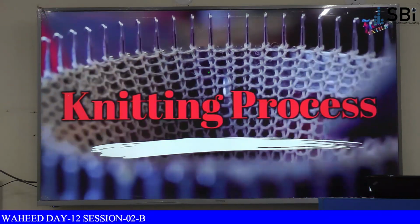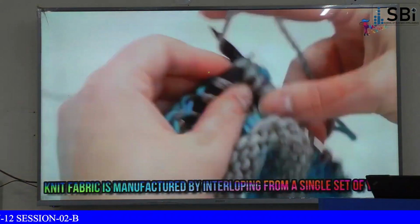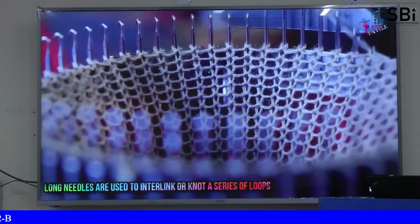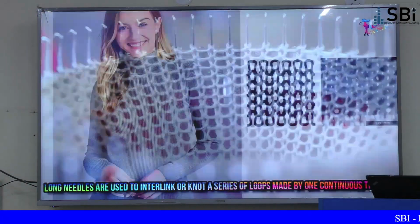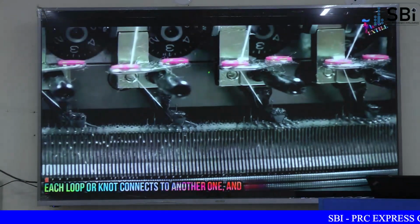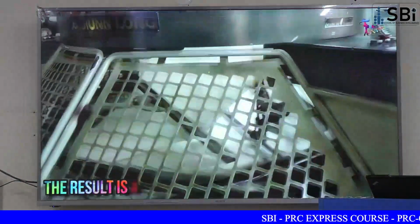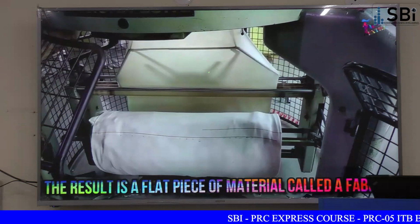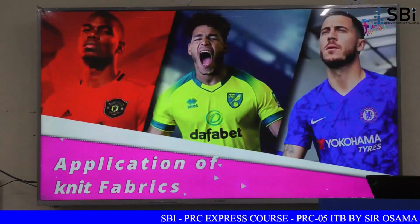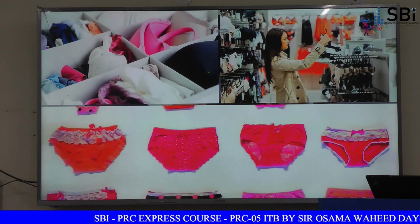Knitting process. Knit fabric is manufactured by interlooping from a single set of yarn. In knitting, long needles are used to interlink or knot a series of loops made by one continuous thread. Each loop or knot connects to another one, and when enough loops have been made, the result is a flat piece of material called a fabric. It is a particularly comfortable fabric structure for sports, casual wear, and also for undergarments.